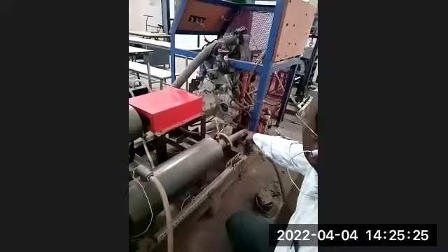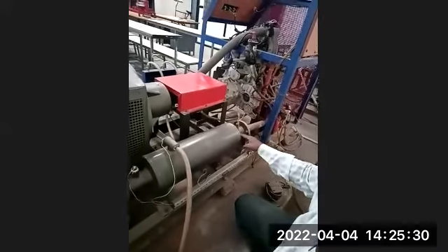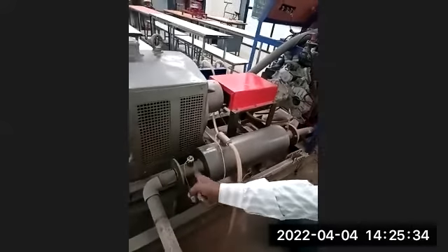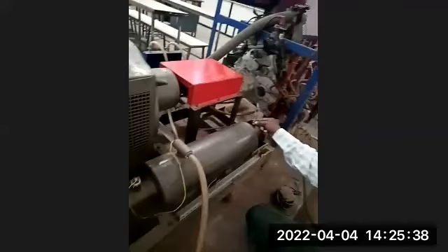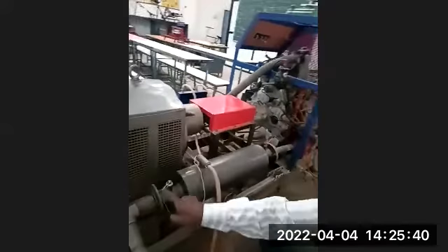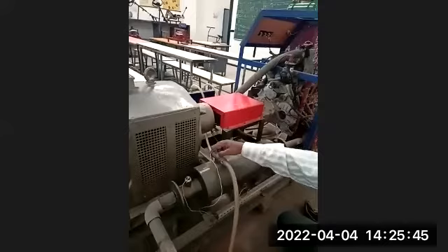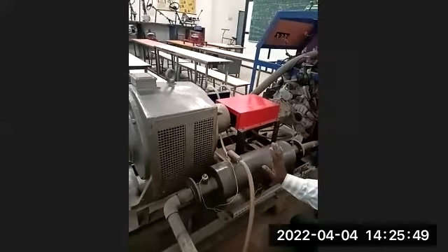Through this particular pipe, your gases are coming from the engine, going into the calorimeter. This is the pipe through which gases are flowing out from the calorimeter. So gases are coming in here, we are measuring the temperature. Gases are going out, we are measuring the temperature. Okay. Now, here, this is the water given to the calorimeter for cooling. So in this particular calorimeter, what happens?